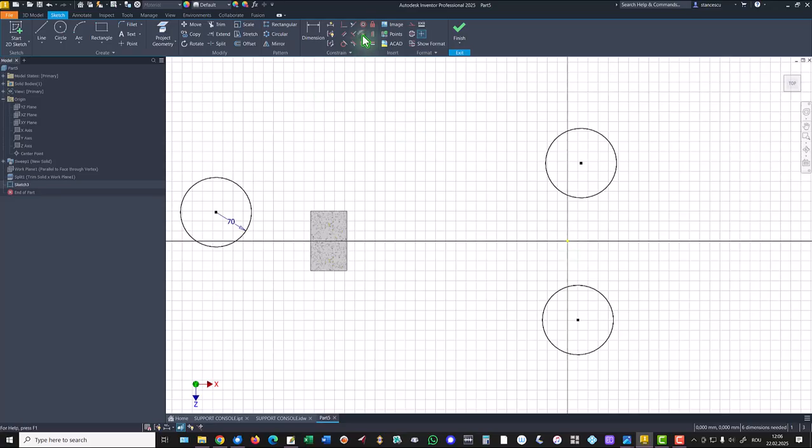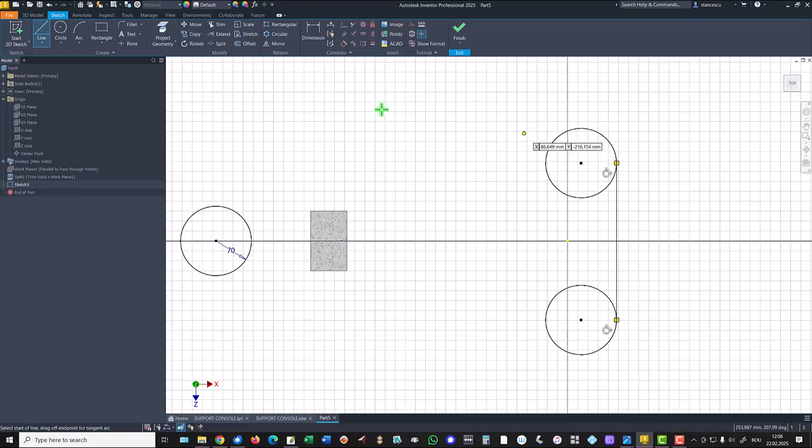We place on the same horizontal this point with the center point. We place on the same vertical the two circles, we draw a line, press the left button and you have a tangent, then go down to another tangent. On the same horizontal is this midpoint with this.